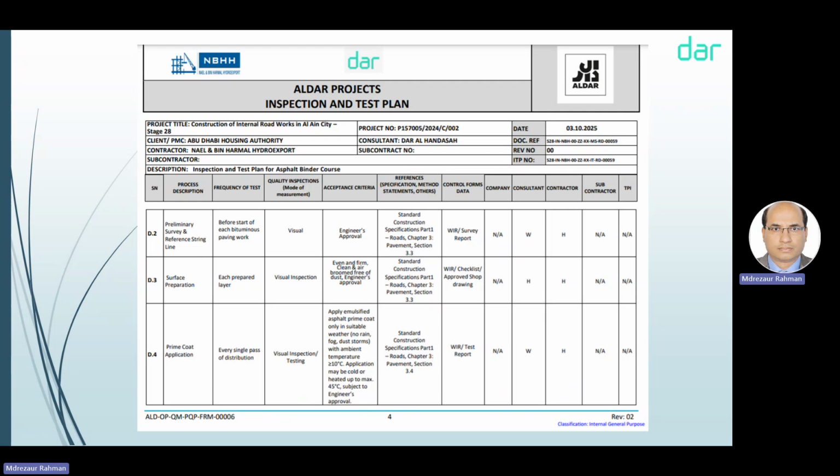Inspection must be submitted. Inspection of the surface and base. Visually checking, sir. Inspection of the surface prior to prime coat. It depends when you are inspecting, but the inspection must be submitted. The document is needed as evidence. So from now, Kamran, surface preparation must be submitted. The mock-up is different. Otherwise, you cannot control, and even their engineers will not accept. Okay, so it is submitted.